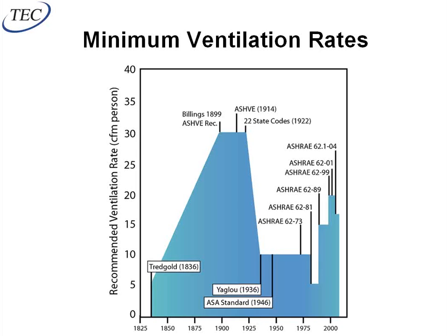So in a typical office building today, the ASHRAE required ventilation is typically 5 CFM per person plus 0.06 CFM per square foot. And for a typical occupant density, that corresponds to about 17 CFM per person. Pretty much the whole point of this discussion is to point out that since 1989 and later is really the only time we've had these higher ventilation rates.